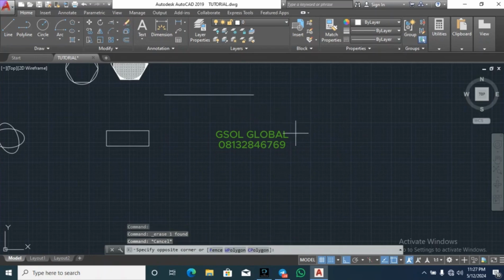All right, AutoCAD provides everything for you. So it's garbage in, garbage out. Whatever you want to do in AutoCAD, AutoCAD will give you, as long as you know what you're doing. So the next one we are having is the copy tool. Let's assume I want to copy an element to a different part of the drawing. The first thing I'm going to be doing is selecting the element and saying, AutoCAD, this is the element I want to apply my copy tool on.